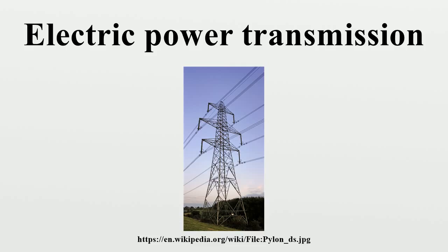Today, transmission level voltages are usually considered to be 110 kV and above. Lower voltages, such as 66 kV and 33 kV, are usually considered sub-transmission voltages, but are occasionally used on long lines with light loads. Voltages less than 33 kV are usually used for distribution. Voltages above 765 kV are considered extra high voltage and require different designs compared to equipment used at lower voltages.